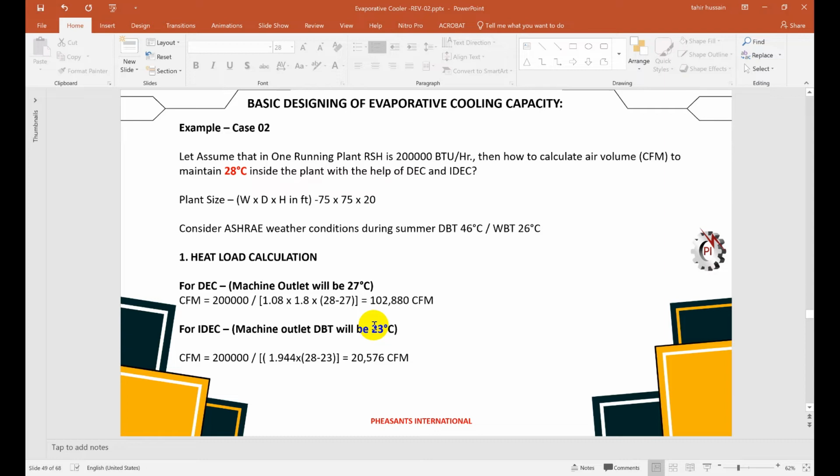in the evaporator cooler machines. Huge saving. And this is the example where it is not a food area. Air changes are not important. We just have to reduce the temperature; maintaining the temperature is important. So these are the two heat load calculations, if we use just the conventional desert evaporator cooler, and if we use the IDEC cooler, 2 stages.